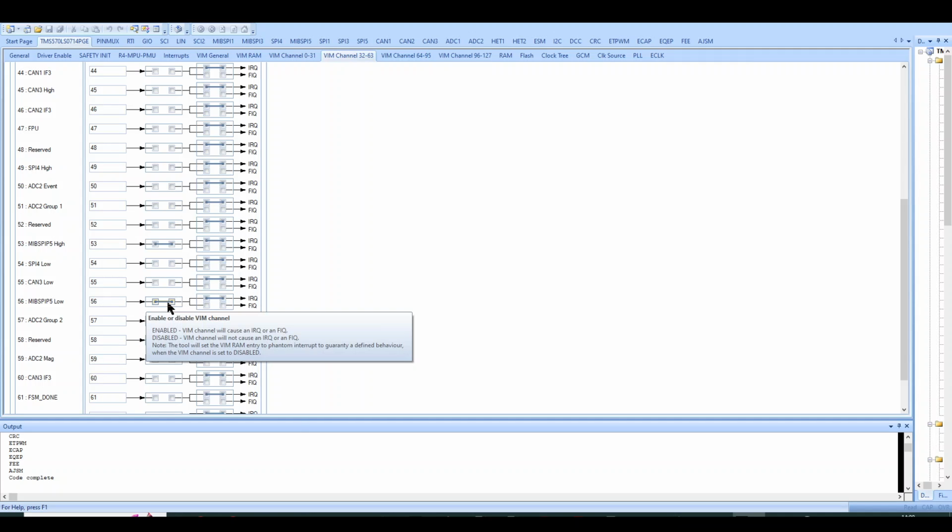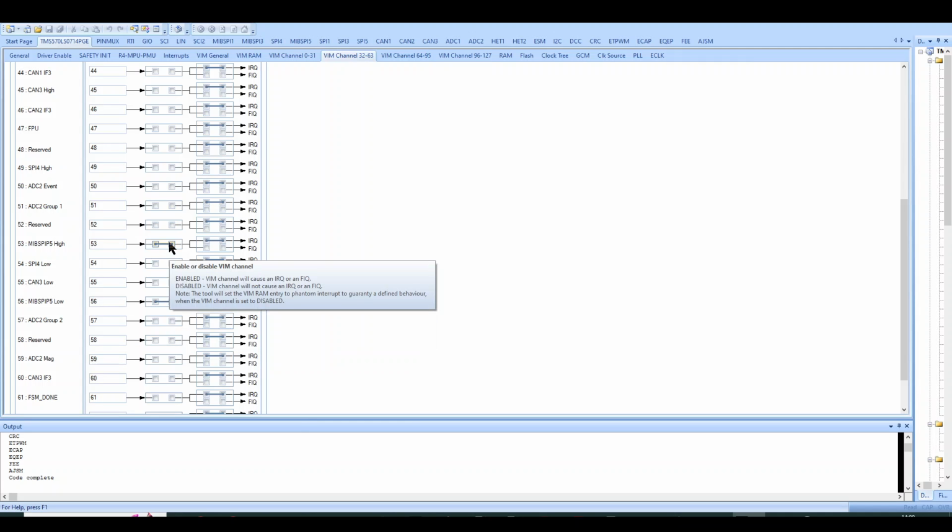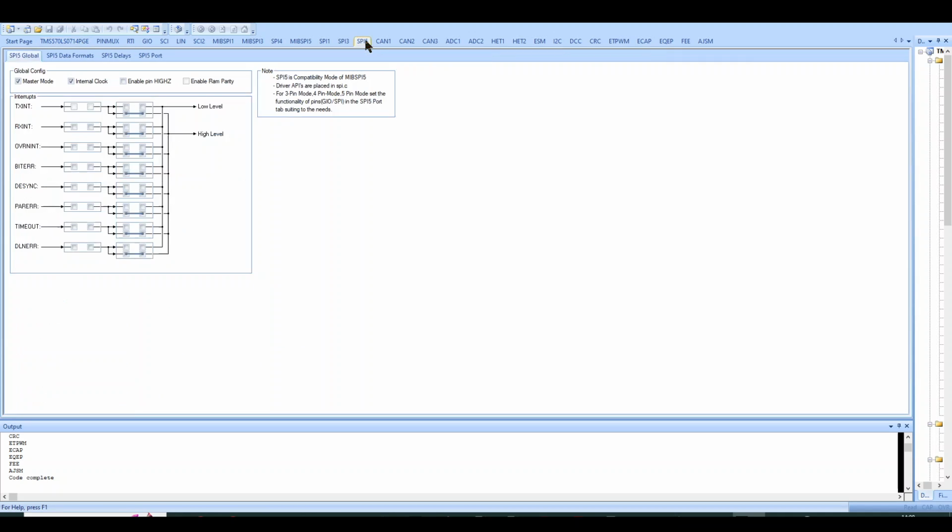So you can see here that I've actually enabled both groups of interrupts, the high level interrupts and the low level interrupts, even though if we go back, I don't have anything connected on a low level interrupt. So in theory it's not possible for me to get a low level interrupt. I've just left it like that for now because I've been doing some experimenting and I may want to change the grouping, but I'm just explaining what does what and how you could set it up.